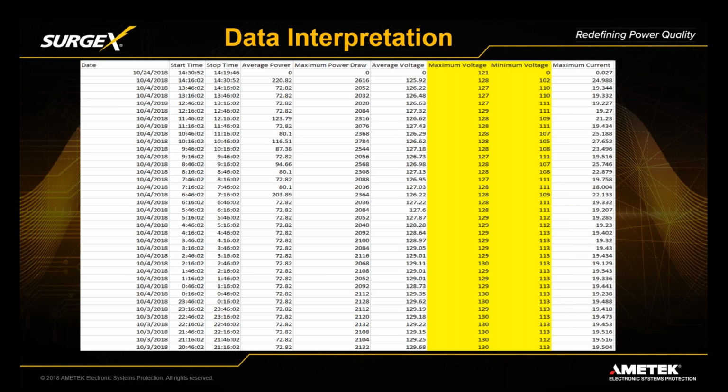It varies a lot, and it's not until you look at these enVision logs to see it. This is an extreme data set that we're seeing here, that it's going from the 112, 113s up to 130 swing every 30 minutes. A lot of times I'll get a data set where 80% or 70% of the data set, the differential between min and max is only 1 or 2 volts. It's like, all right, that's pretty stable.